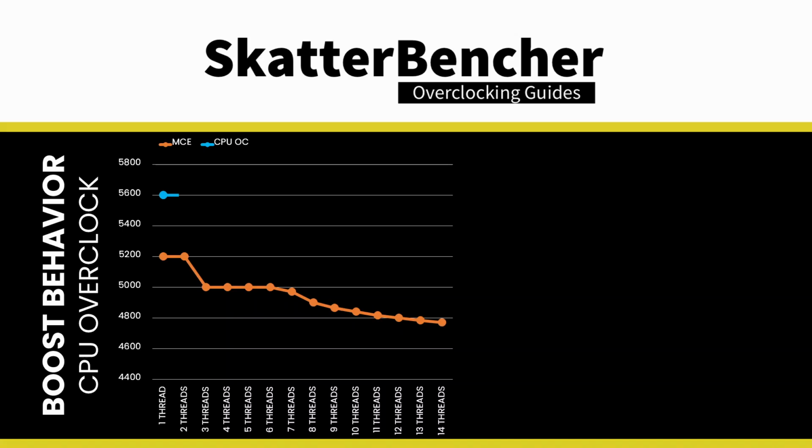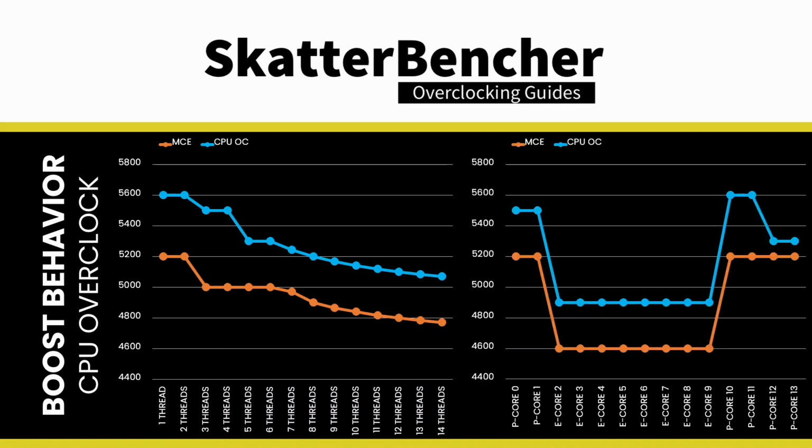the CPU boost frequency with one active P-core is 5600 MHz. The average boost frequency gradually trails off to 5300 MHz when all P-cores are active and 5071 MHz when all P and E-cores are active. In single-threaded applications, 2 P-cores can boost to 5.6 GHz, 2 can boost up to 5.5 GHz, and 2 to 5.3 GHz. Every E-core can boost to 4.9 GHz.